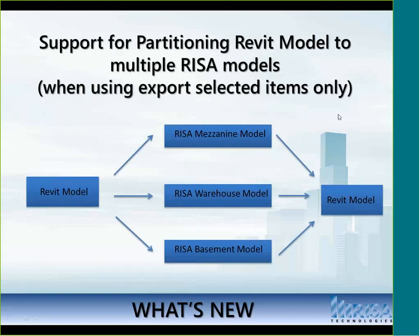Another big new feature is we have now added full support for partitioning your Revit model. What does this mean? Well, let's say that you've got a giant Revit model, and that Revit model consists of multiple independent structures that you want to handle in separate RISA models. Well, you can take that Revit model, and using the Export Selected Items Only option, you can export out from Revit into multiple different RISA models.